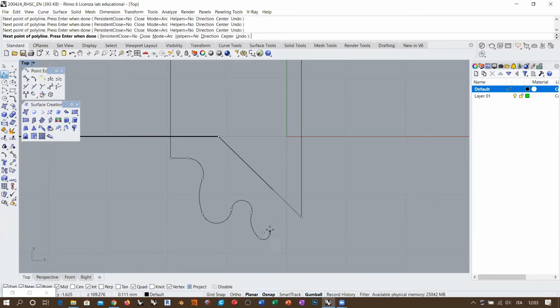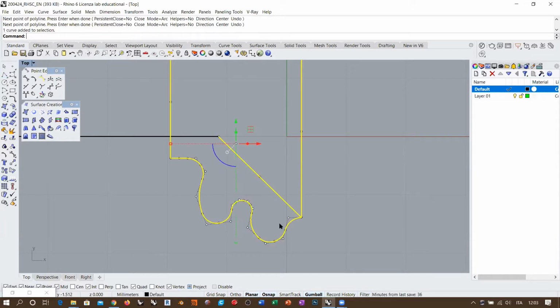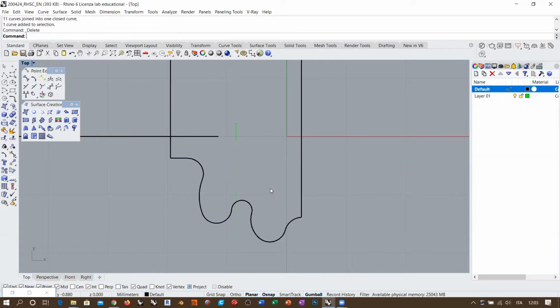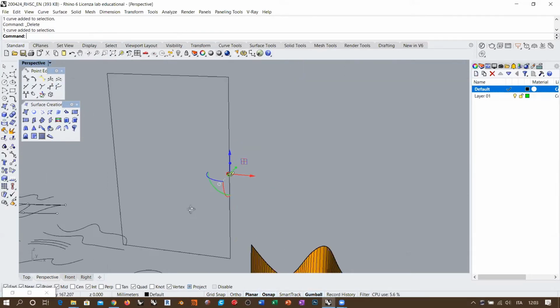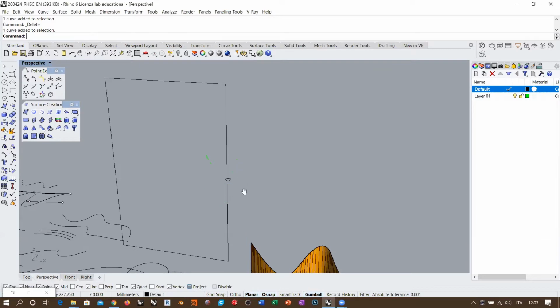So I'm basically designing something like the frame of a picture or something like that, and then reach this point. Okay, then I take this polyline here, explode it, get rid of this line, and join it back again. So I have one closed polyline in this case, which lies at half the height of this frame.